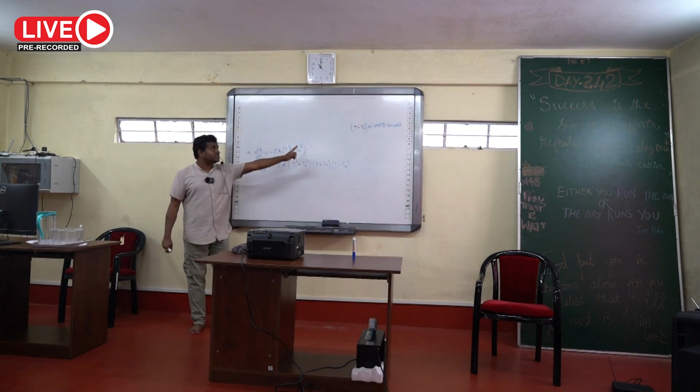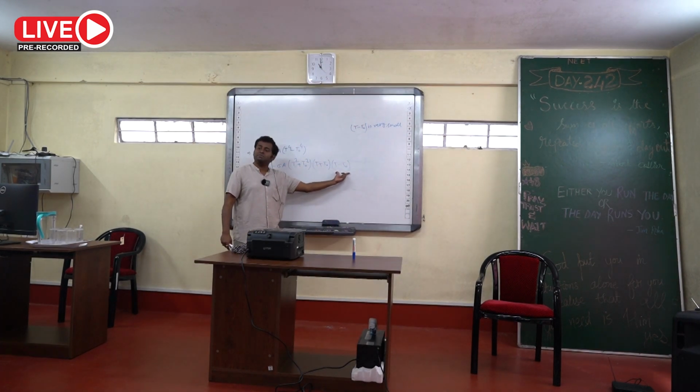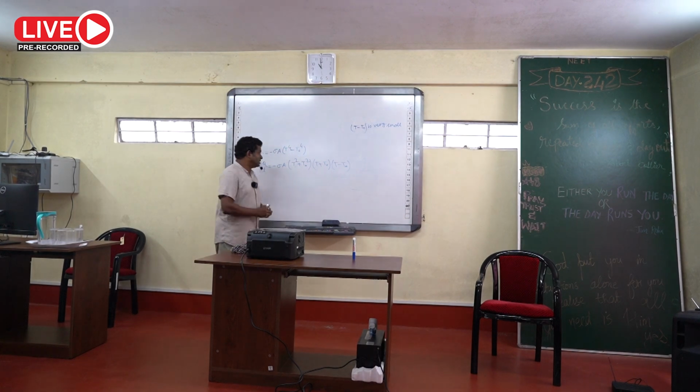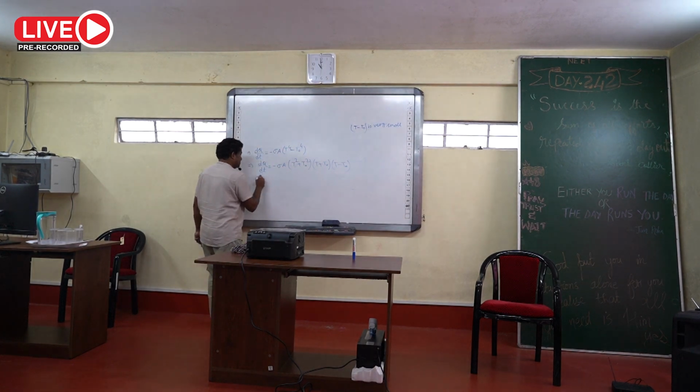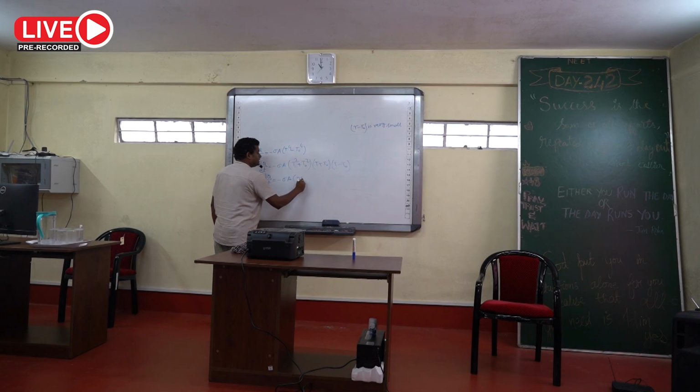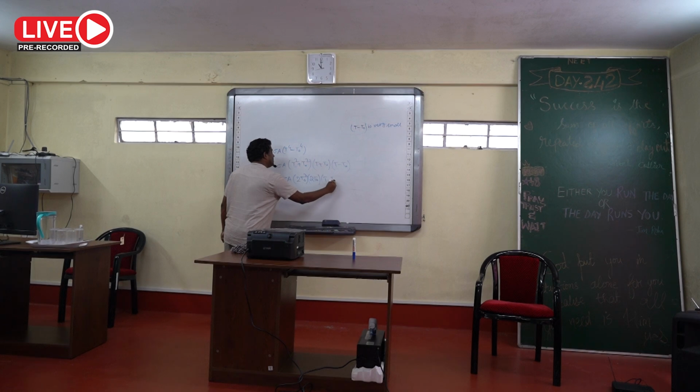Since the difference is only very small, we keep this term, and in the remaining terms we put T almost equal to T naught. Then dQ/dt equal to minus sigma A, this one will be 2 T naught square, then 2 T naught, into (T minus T naught).